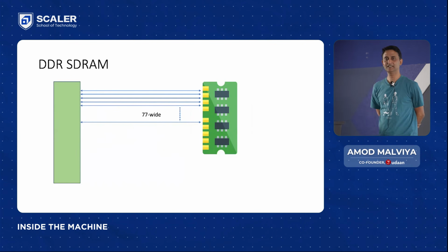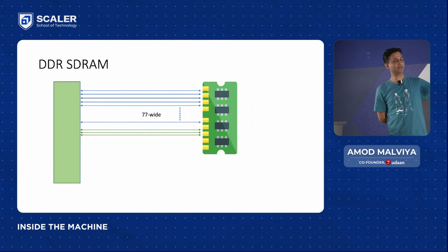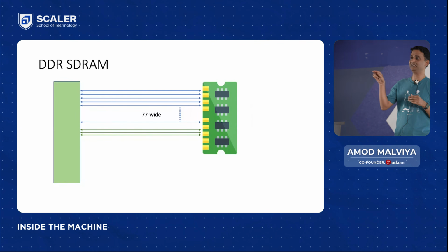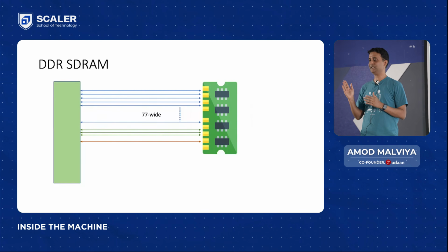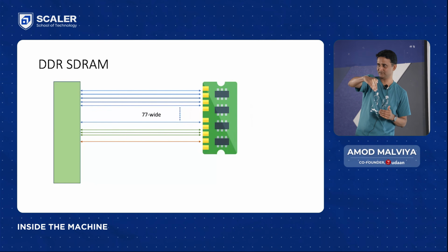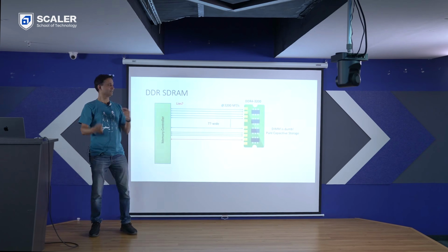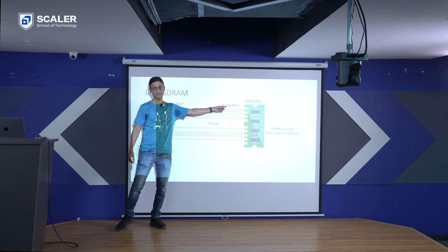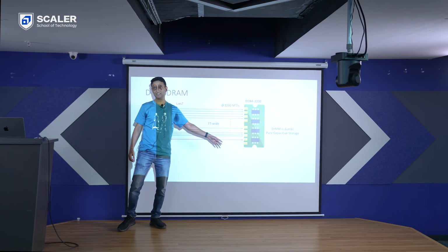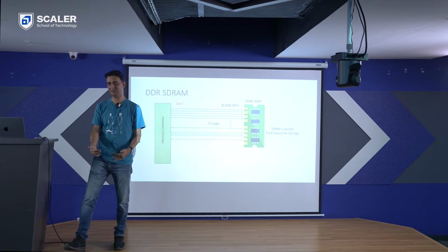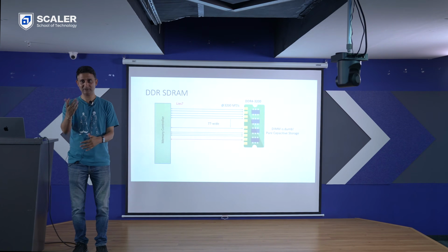3200 megahertz. Remember the double data rate, right? Double data rate means that at every clock, we send data both at the leading edge when the signal rises from 0 to 1, and then at the falling edge, 1 to 0. Okay? So in one clock cycle, we are sending 2 transfers. Which means that if transfers are at 3200 million transfers per second, clock speed is going to be 1600 megahertz, just to be clear. But were you saying that 3200 is a lie?